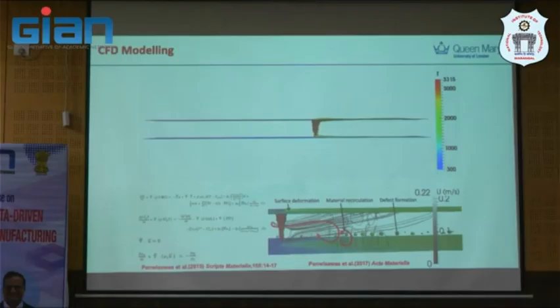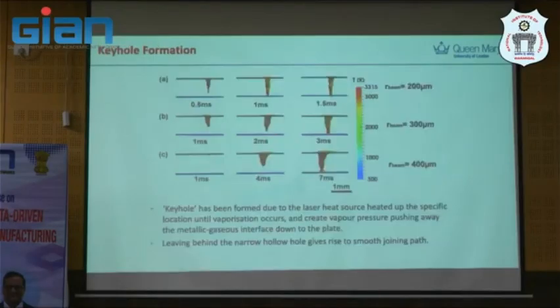And I can say that after we published the work, a lot of work came out, and you may see more and more in additive manufacturing that they can predict the dynamics of this very well, probably a lot better than us, the first approximation here. But anyway, we capture all the surface deformation and material recirculation, so this may cause the streak of porosity, which is trapped inside the fusion zone, and then they will have defect formation here.